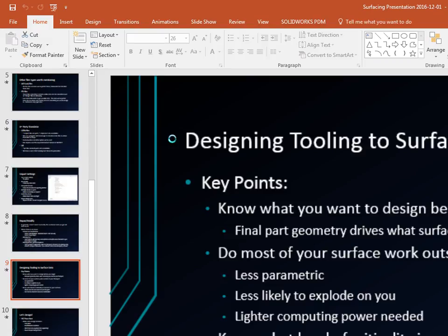And then I'm just going to take on this plane, draw a sketch, planar surface. Okay, so I'm going to replace face. I'm going to replace this face with that surface. Boom. That's about the simplest you can get, but it does work when it's somewhat simple like that.